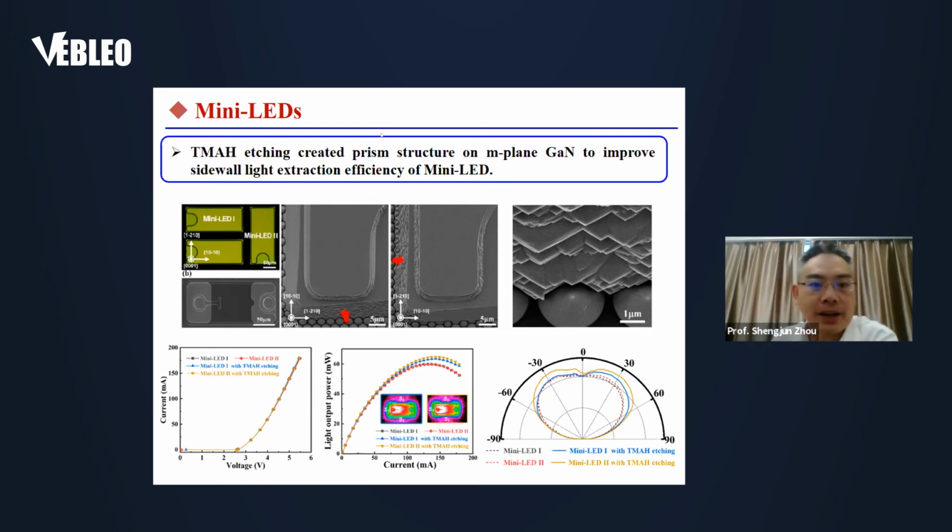This direct writing was applied for fabricating nickel gold wire grid as transparent conductive electrode for UV LED. Nanoscale nickel gold wire grid shows better transmittance than ITO transparent conductive electrode in the UV LED wavelength region.